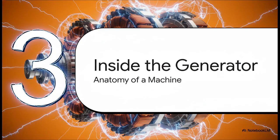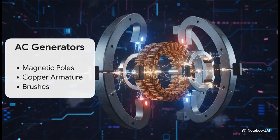Okay, let's get into section 3, inside the electric generator, anatomy of a machine. Let's essentially crack one of these open. An alternating current, or AC generator, relies on 4 main physical parts. First up, you have the stator. These are the fixed north and south magnetic poles that provide that constant, imposing magnetic field. Suspended right between them is the armature, which is this tightly wound, spinning copper coil wrapped around a metal core.